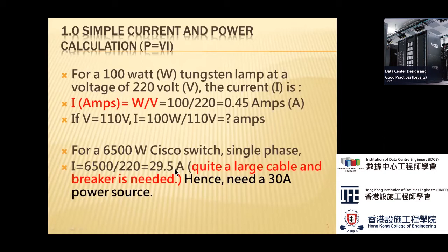But here, why has the current increased? Because the power has been increased as well, right? The 6,500 watts instead of 100 watts. So that's why the current has increased, and so has the cable size. Now, don't forget, we're working on a single phase at the moment.